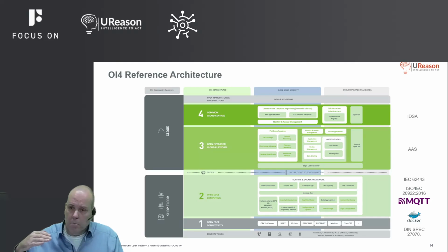We take data from the field level in multiple different protocols, 4-20 milliamp, IO-Link, Profinet, Profibus, but of course also Modbus, EtherCAT, and other connection protocols. And we've defined a reference architecture where at the edge level, so that could be in the cabinets or it could be on-premise where your SCADA data historians are located, some heavy processing on the data is already performed before it's communicated upwards, northbound, to cloud platforms that provide you with maintenance management functions, cloud platforms that allow you to benchmark performance of your assets across multiple sites, for example.